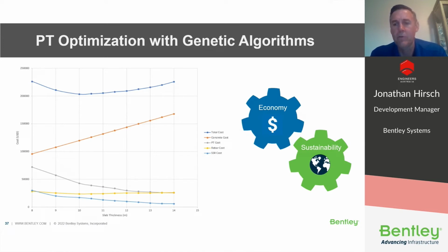So using an optimizer, the general parameters were set up, and each different thickness could be optimized in parallel with just a few seconds of additional effort. So the total cost results, represented by the dark blue line, you can clearly see where the minima is there. In this case, it's a slab thickness of 10 inches. And this conclusion is backed by thousands of real calculations on trial slabs of all representative thickness, so that the engineer can have confidence in this result.